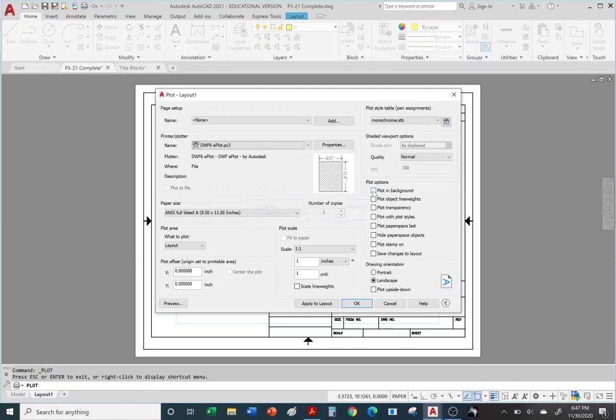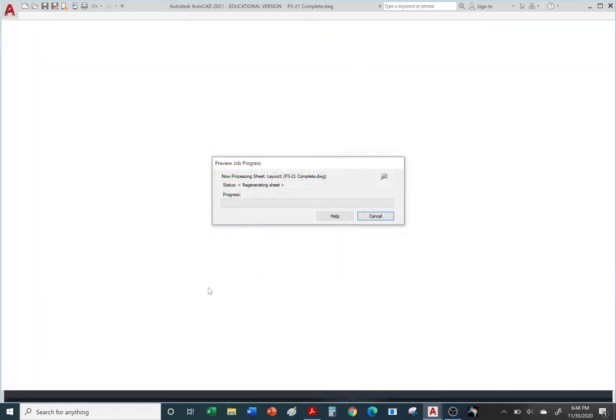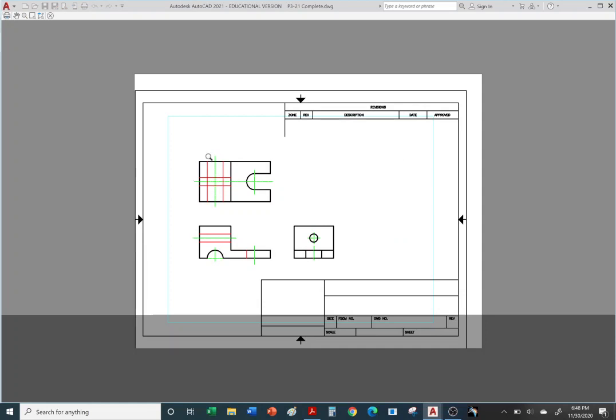And once again, when you're ready to print, before you print, go to Plot Line Weights, Plot Width, Plot Styles, and Paper Space Last. So here I do have the option in Layout to click these options. Make sure you pick Monochrome. And let's hit Preview one more time. Preview. You can see the lines are a lot thicker. Looks a lot cleaner. And by picking Monochrome, these light colors will not come out gray. They'll come out with a nice black thin line, thinner than the object lines.